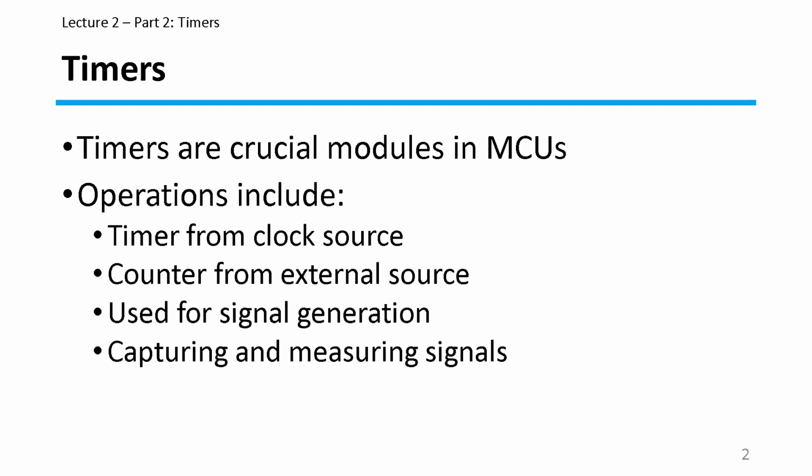In your microcontroller, everything and every operation is executed in clock cycles, but that clock cycle is dictated by the crystal frequency or the clock frequency. So different boards will have different crystal frequencies, and you should refer to your board schematics or your microcontroller unit's datasheet to determine that frequency.